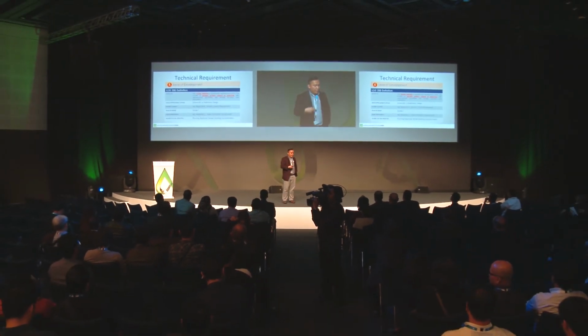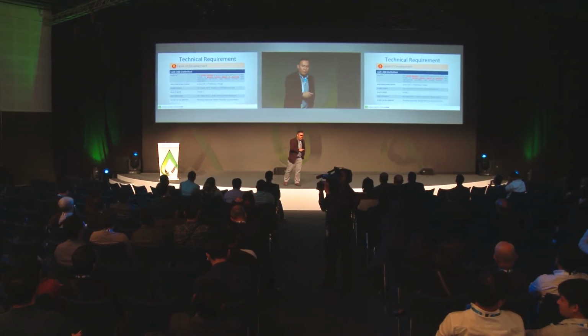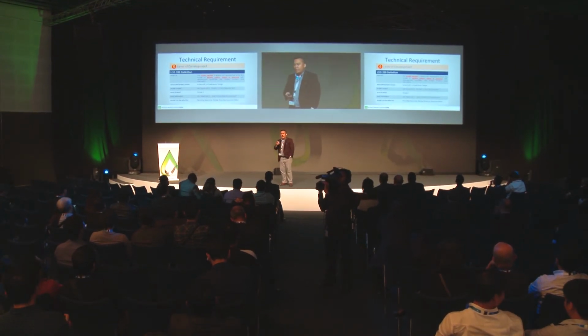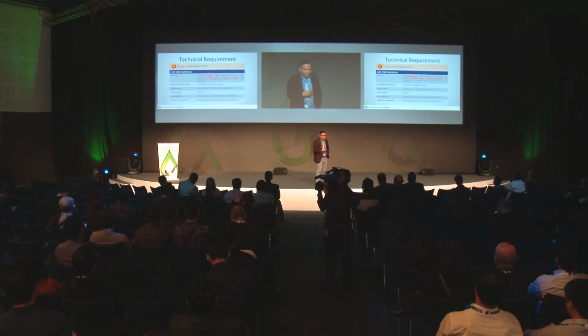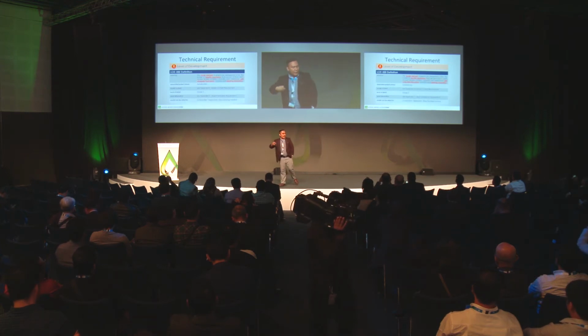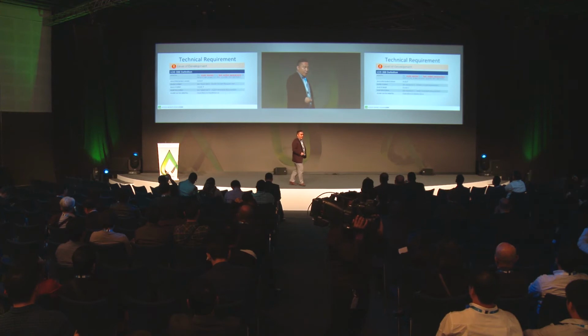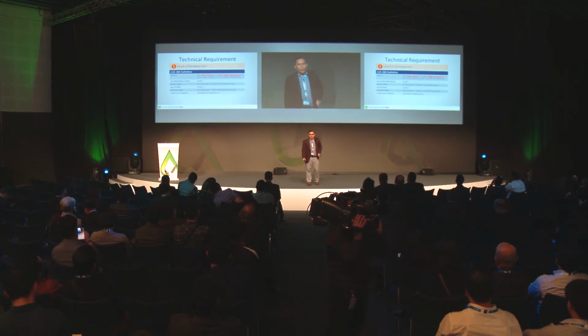Okay? And then we have level of detail. So for LOD 200, we define level of detail at minimum grade 1. And then asset information, this is basically the information required by the client, unique to the facility that we are building. And then, of course, at LOD 200, the model can be relied on for planning approval and tender documentation. And then 300 is the same, 400 is the same, 500 is the same. So we have clearly defined the definition of level of development.